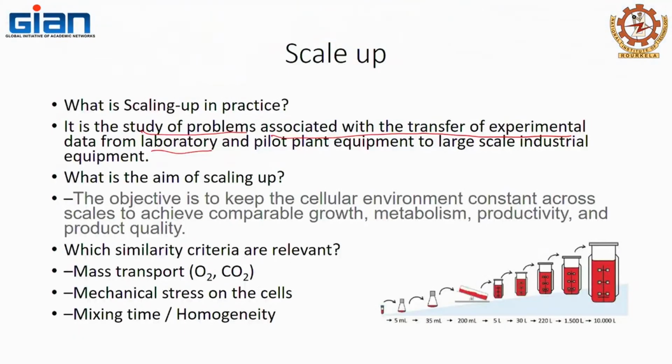So, what is scale up in practice? Scale up is the study of problems associated with the transfer of experimental data from laboratory and pilot plant equipment to large scale industrial equipment. So, you are starting from a test tube to a 5 ml flask, 35 ml flask, 200 ml flasks.